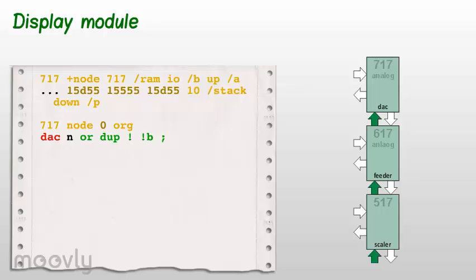We know that the value is provided by node 617, therefore we need to read down port. However, both registers A and B suitable for addressing are already used. We may use, for example, A register, load down port address into it, read a new value, and then load the register with up port address again.